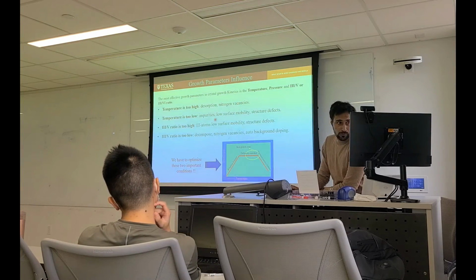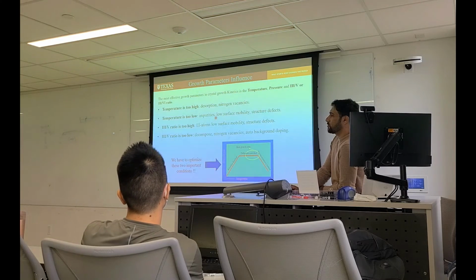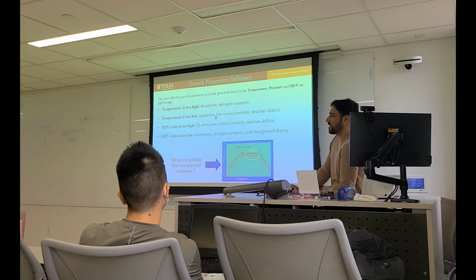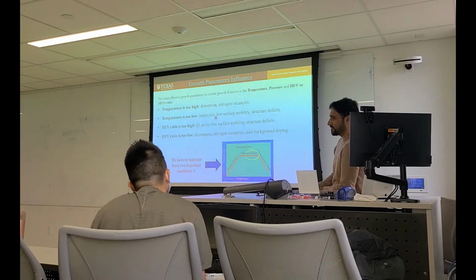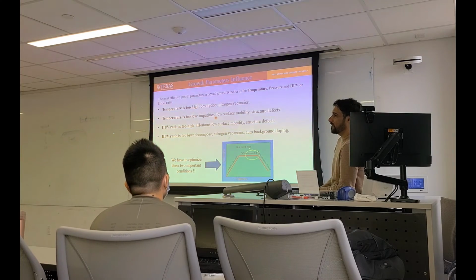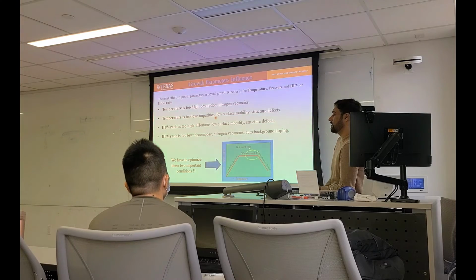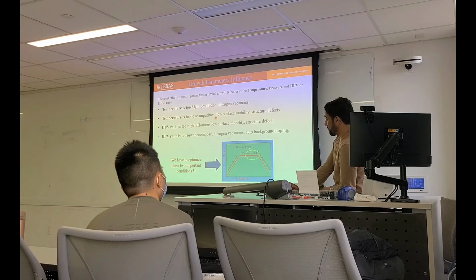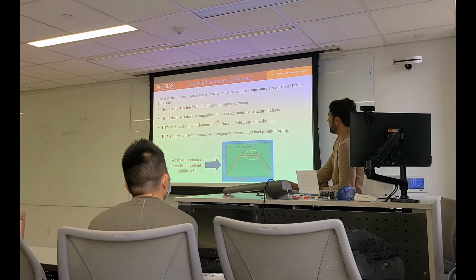If temperature is too low, you get impurities, because you are using metal organic precursors, which have carbon. There are also other impurities inside the reactor because you are using it again and again, so they lead to memory effect, and those are the impurities. That's why we have high electron concentration in undoped gallium nitride, because of the impurities and defects. Also low surface mobility: because temperature is low, diffusion length is reduced, and then ultimately you will get defects.